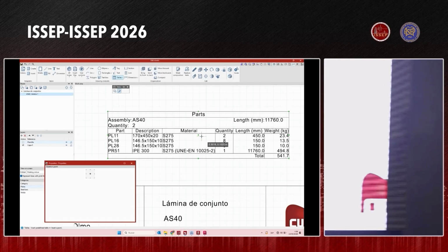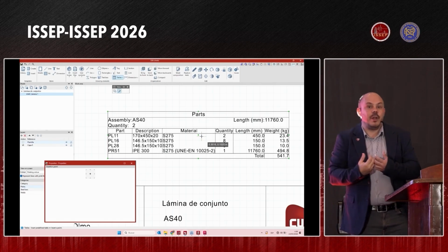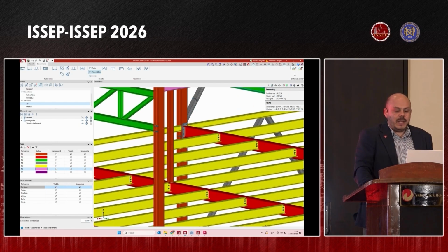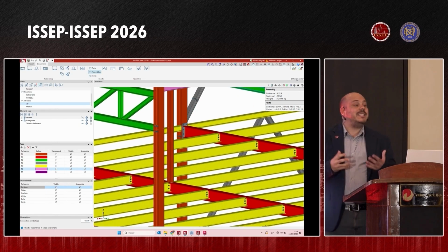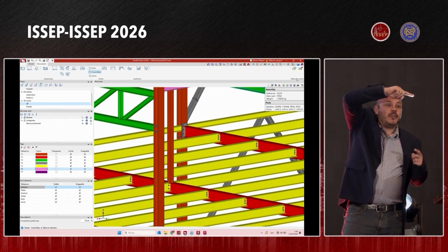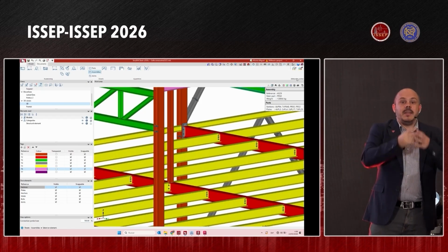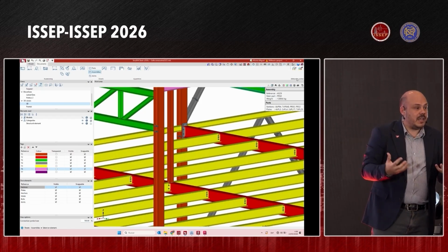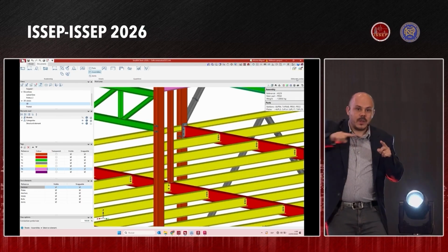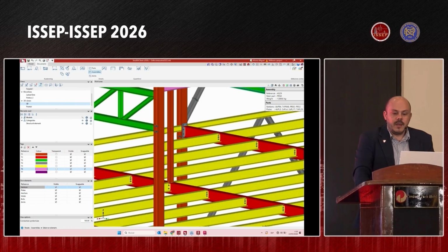So automation, because now we are using the part that is the Building Information Modeling that came from our analysis, okay? Very good. So in case we need, we can use the platform, the common data environment that we presented yesterday, to send this model back to the first software and feed all those nodes with new values of rotational stiffness, and then we can recalculate the structure with a more precise number. So it can also feed back. It's not just one way, it's a cycle, okay? It's a cycle.